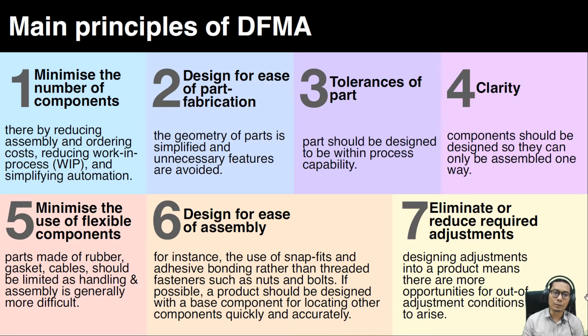The fifth principle is to minimize the use of flexible components. So parts made of rubber, gaskets, and cables should be limited as handling and assembly is generally more difficult. It's pretty difficult to proceed with the assembly process if you design a part which is made of rubber, gasket, cables, and so on. And a few other examples of this.